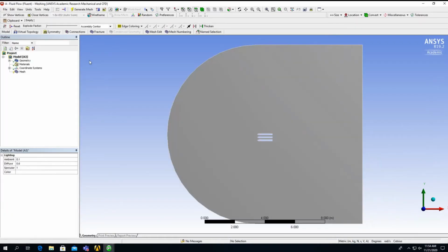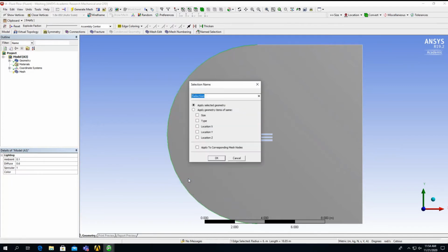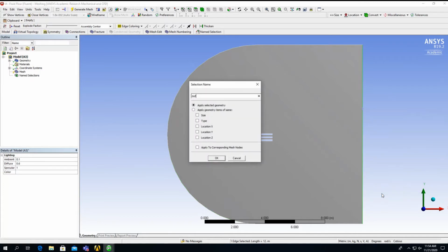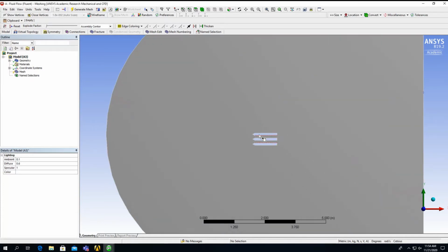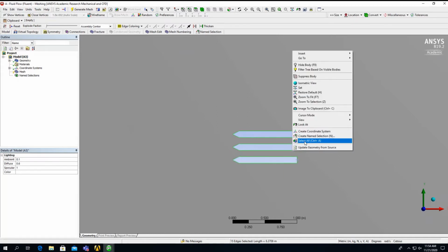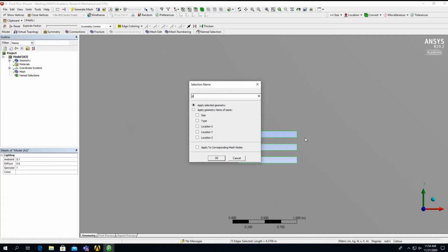After the geometry is done, we then can proceed to do the meshing. Here we are naming the different entities. First doing the arc circle as the inlet, the back face of the rectangle as the outlet, and the pontoons as pontoon walls. The other two sides of the wall don't need to be labeled as ANSYS will acknowledge them as walls in this case. This is to ensure that the different entities are labeled.